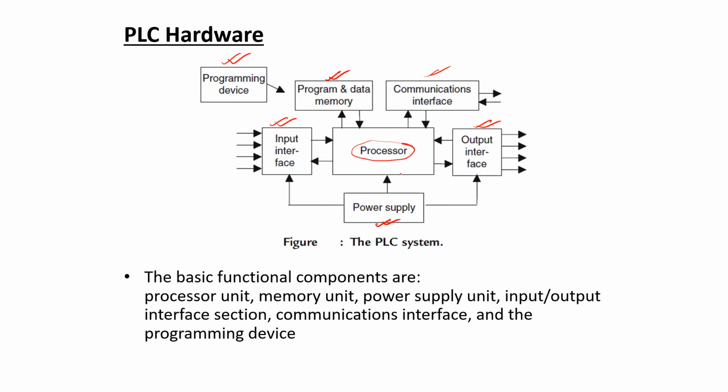So maybe the microprocessor or the input output interfacing units are designed to operate at 5 volts. Then the job of the power supply unit is going to be regulating the input supply, which might be an AC supply, into the desired 5-volt level, so that the microprocessor and the other units can function properly.